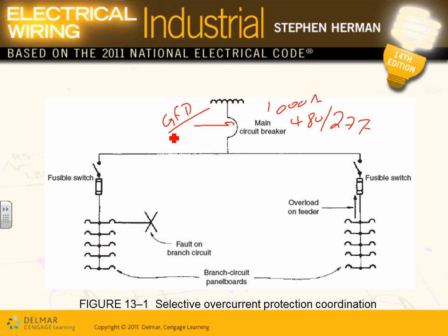So if I have a ground fault anywhere in this system, it could be sensed and trip the circuit breaker on ground fault. When I was your age, guys, and we talked about ground fault, it confused me. What's the difference between ground fault and short circuit? Short circuit is phase to phase, or phase to phase to phase. A ground fault is any phase to the ground.